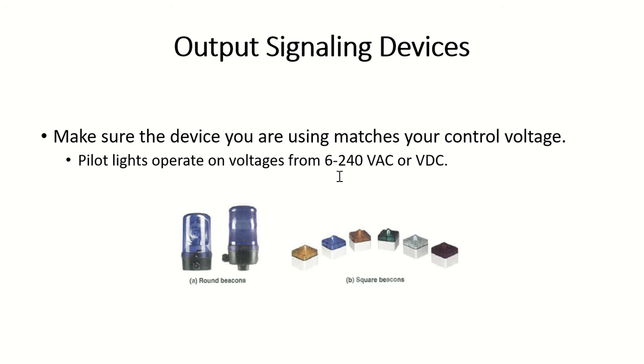Just like you would know not to wire multiple lights in a house in series, because the more you put in series, the dimmer those lights are going to get. The same rule applies for motor control equipment. So again, make sure that they are not in series. When you want to put multiple lights on, we're going to put them in parallel. We can still use those same input switching devices to control 1 or 2 or 3 lights. We just have to make sure that they're in parallel in those rungs.